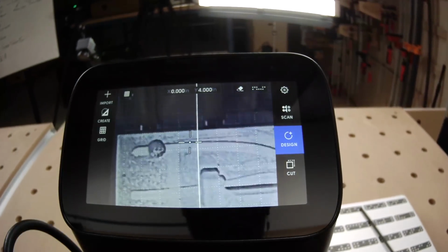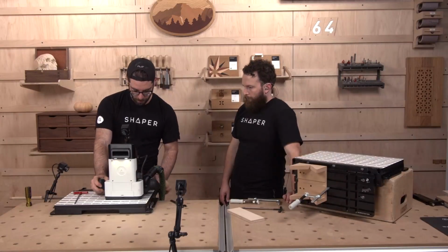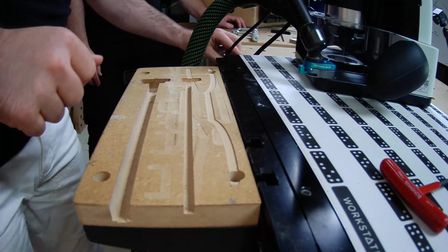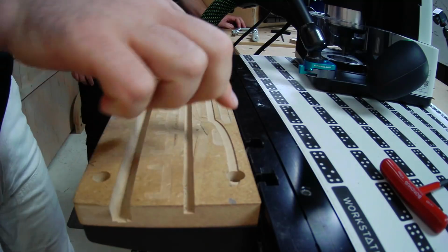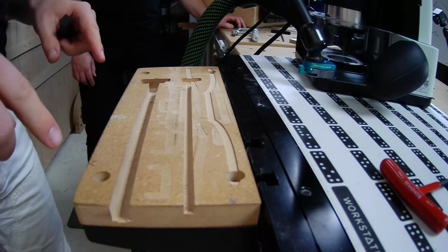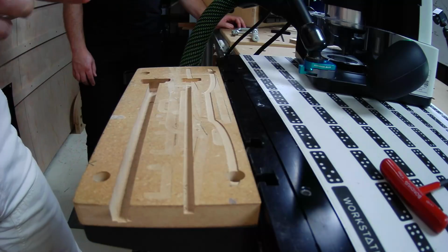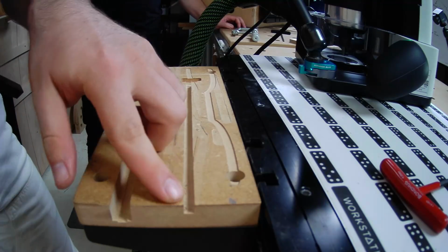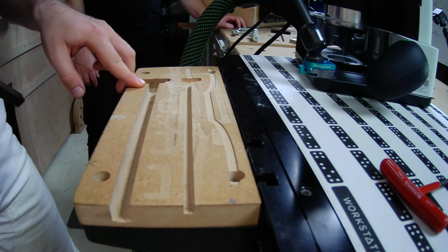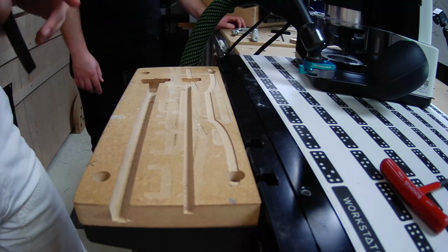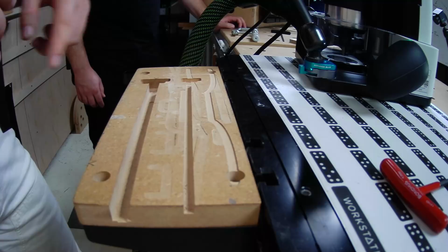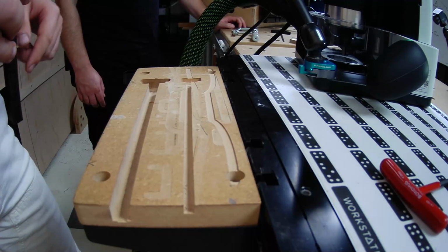So I'm going to move away for a second so that we can show the setup of this. We've got this fixture here, which is pre-machined, and the important thing to look at with this, because this is a spoil board that's been used a couple of times, are these two tracks. We've got this long track here and this long track here. These are the fixture slots for 1/2 inch and 1/4 inch screw hole cover plugs.